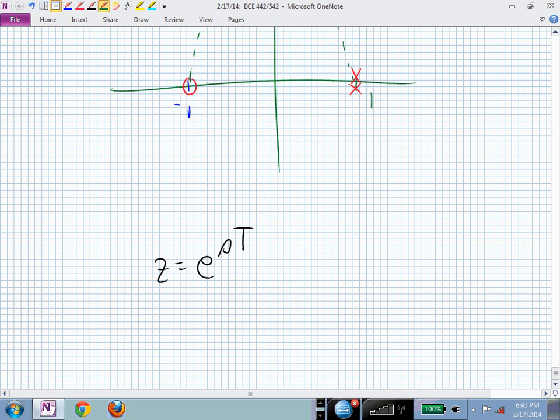But now that's another zero-order hold equivalent. What if we looked at a pure integrator? We've looked at a constant. We looked at basically 2 integrators. That's a pure mass. What if we step back and look at just a pure integrator, and maybe we'll look at an exponential system. What are their zero-order hold equivalents? And we'll start to build up this feeling for what capital G of Z's look like relative to what G of S's look like. Those are our zero-order hold equivalents. Are there questions on that?